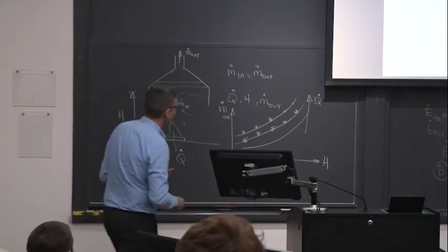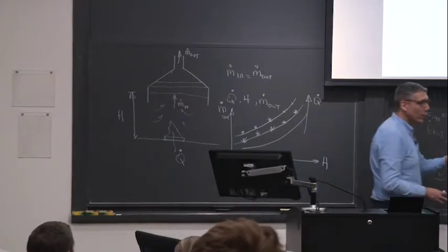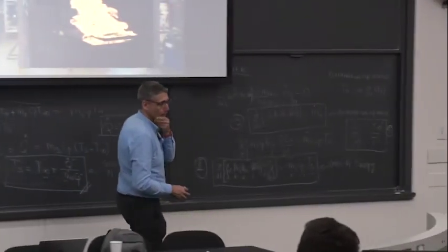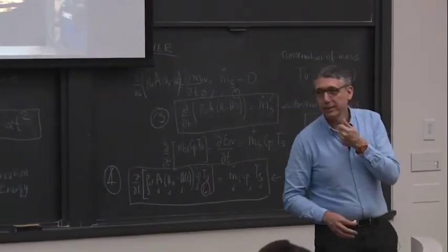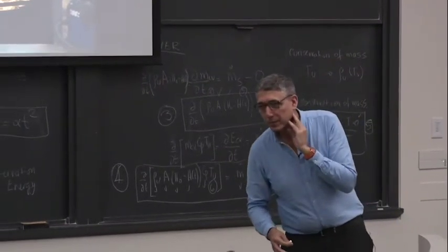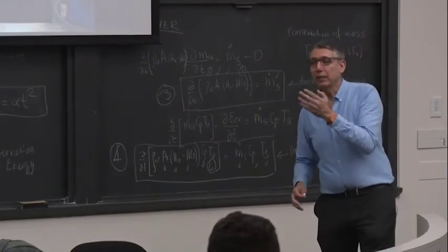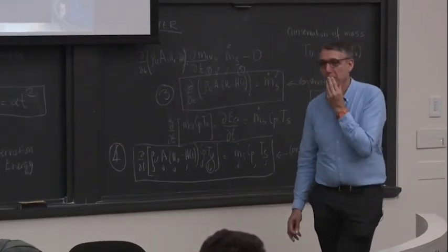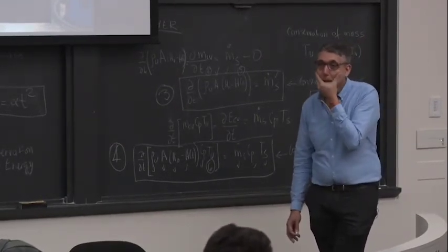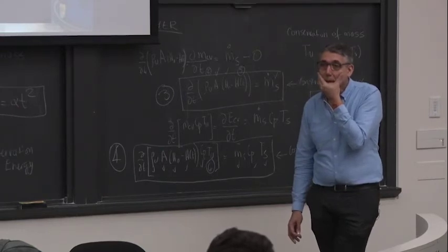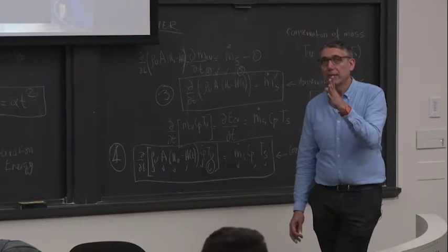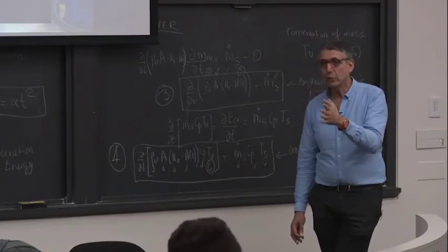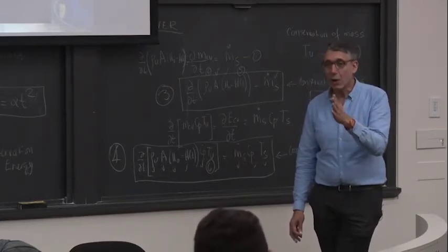Exactly. So we have to non-dimensionalize it. So how do we non-dimensionalize it? Why would it be the height of the flame? I mean, think about it. Yes, but you see, the flame is related to the heat release rate. But how is it related to the variable I'm interested in?